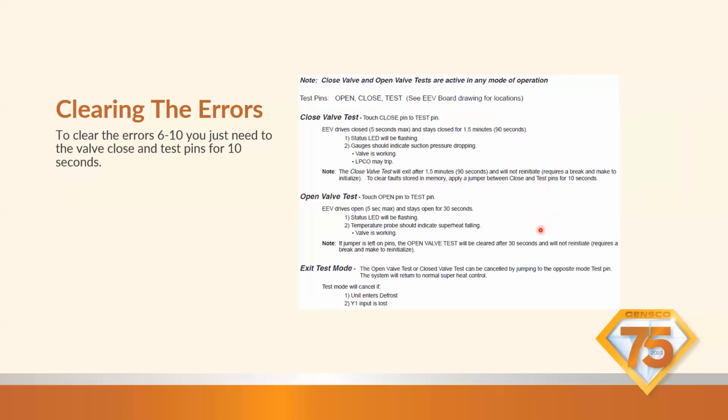That being said, I don't like people who count to 10. 1, 2, 3, 4, because a lot of times people count too fast. I've had multiple people who did it and they only held it on there for 9 seconds or 8 seconds because they counted too fast. And if you do that, it doesn't clear anything. It just does a closed valve test. That's all it does for you.